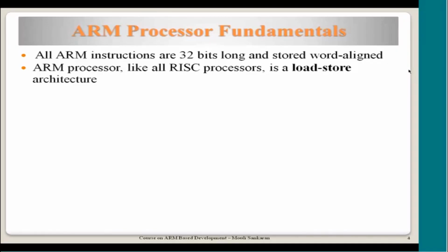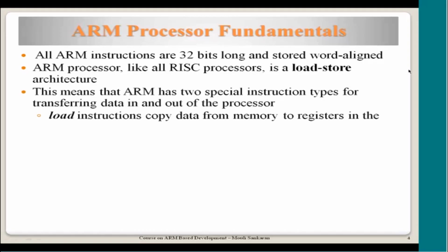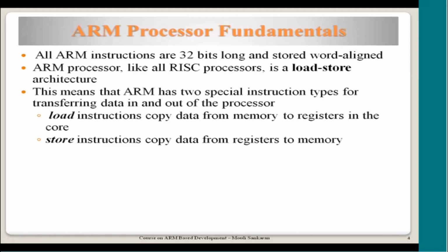And as you are aware, this is a RISC processor with a load-store architecture. That means anything to do with memory is done using load or store instructions. If the processor wants to read a particular piece of data from memory, it has to use a load instruction, and if it wants to save any value in a register to memory, it has to use store instructions.